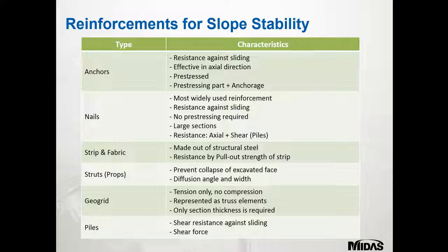The table shows some of the common types of reinforcements which can be considered in soil works. Anchors can be defined to take actual loads, and which can be pre-stressed, and they can also be grouted types of anchors that can be modelled as well.